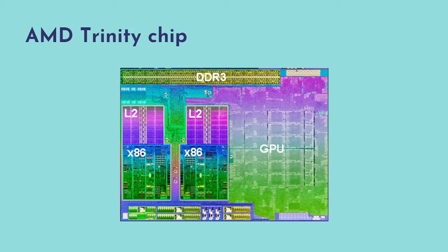In AMD APUs, a programmable x86 CPU and the vector processing architecture of a GPU are both joined together on a single piece of silicon by a high performance bus. Both have local access to high speed memory. AMD APUs also include a variety of other system elements such as memory controllers, I/O controllers, specialized video decoders, display outputs, and bus interfaces.